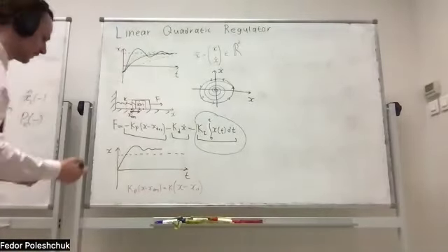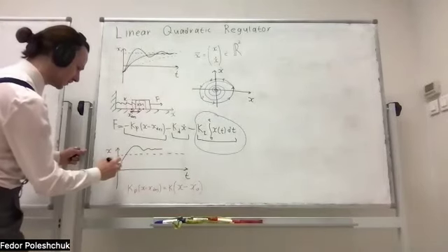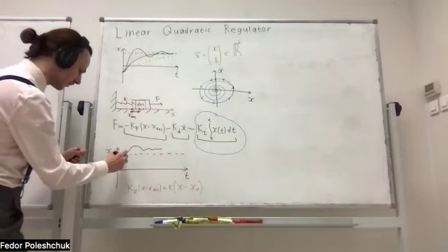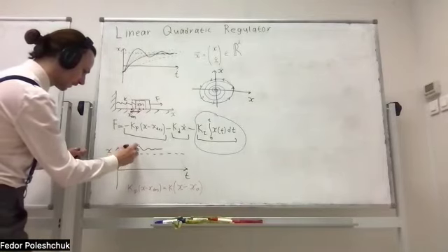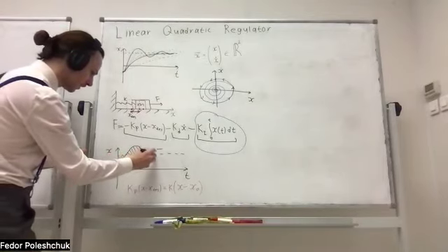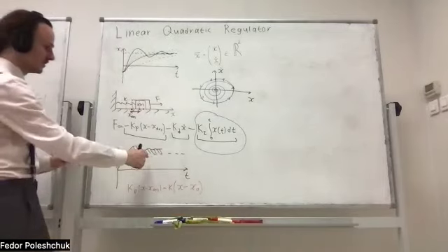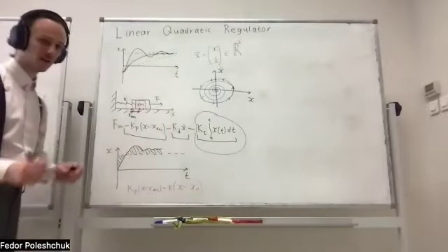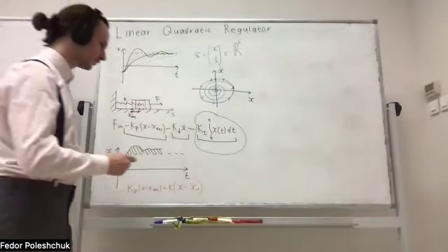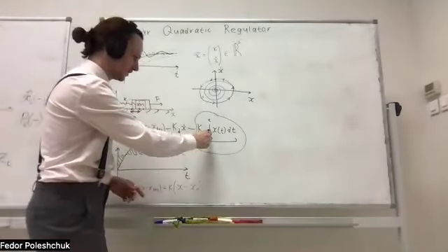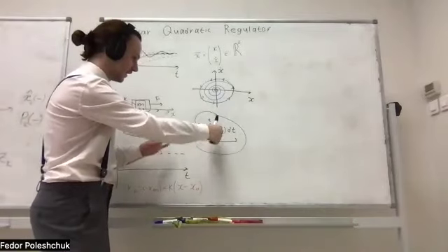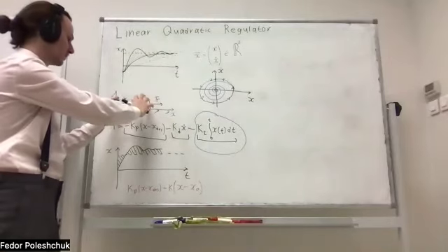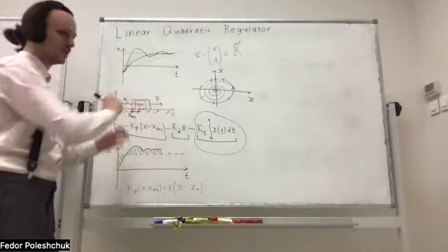And what is that exactly? The integral term of the deviation will be equal to the area under this curve. And here you can clearly see that over time, this area will increase, and thus this integral will increase, and the force will increase as well. And eventually the block will start to move to the desired position.